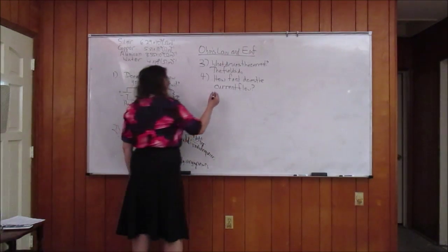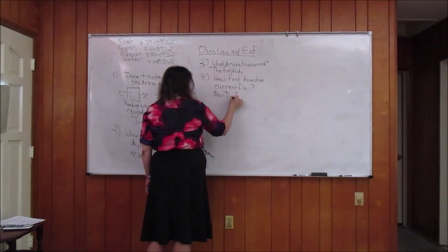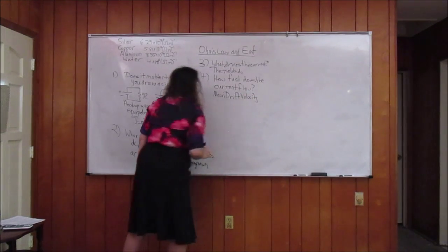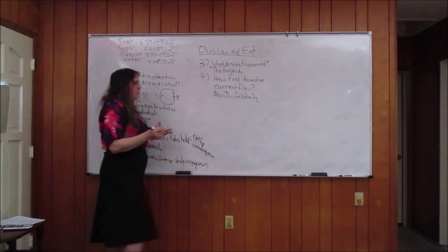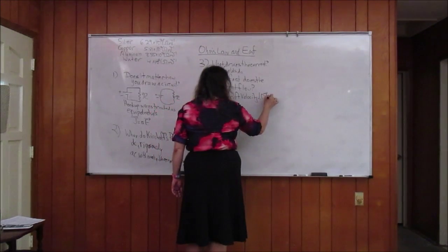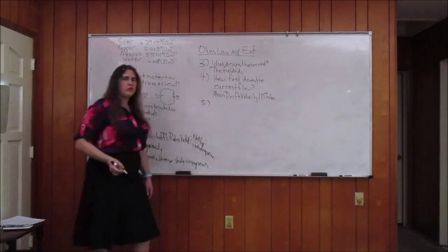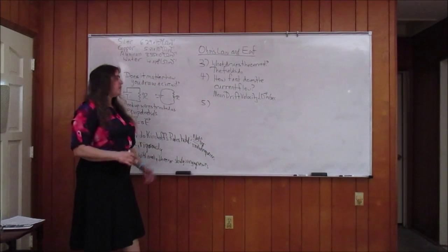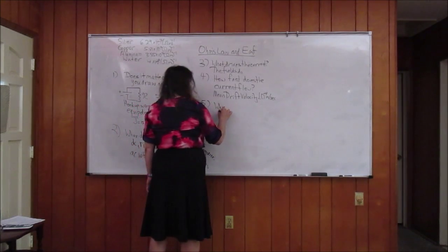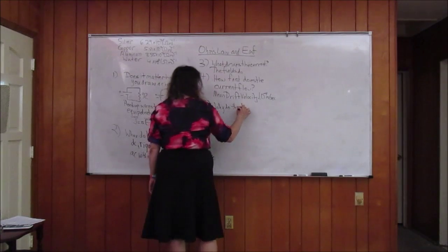So in fact, there's a mean drift velocity, and that has a value somewhere on the order of magnitude of 10 to the minus 4th meters per second. So that begs another question. When you flip on the light switch, why does it take forever for the lights to come on? Why do the lights come on almost instantaneously?